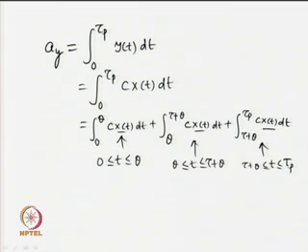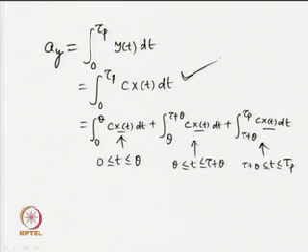So, keep in mind, one cannot make use of a single expression to find the area of the output signal, because we have got 3 different piecewise constant inputs to the system, which change their magnitude at different instants of time. Therefore, the piecewise constant inputs are to be considered definitely to find the correct expression for the asymmetrical output of the system.